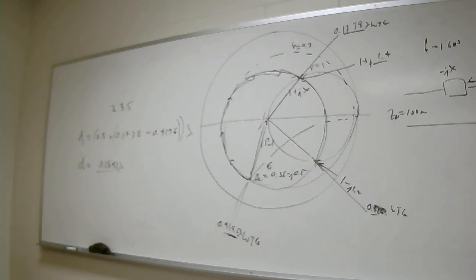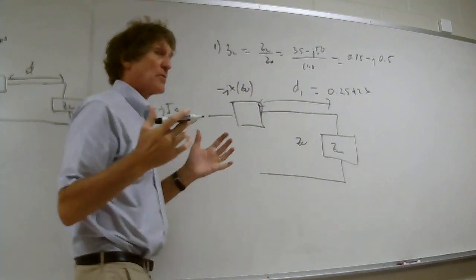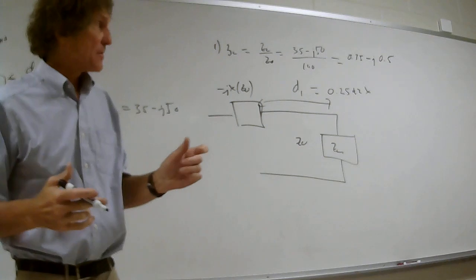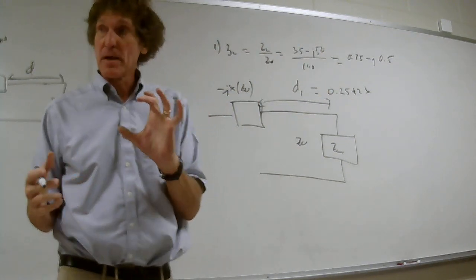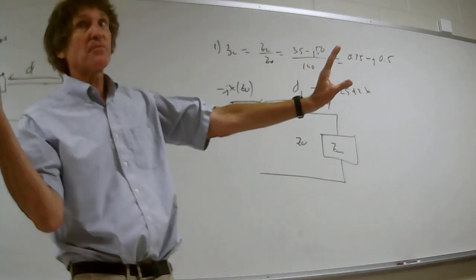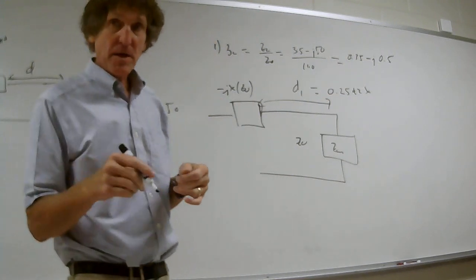And when we hit this point, we have to add a minus jx normalized impedance. But that means the actual impedance would be minus jx times Z naught because it's non-normalized. Can everybody follow the rationale behind that? When we add that together, this will cancel the reactive component and you'll just have Z naught. That's the way matching works. You want the thing to look like Z naught. You come from Z naught, you go into Z naught, there's no reflections. That's the idea.